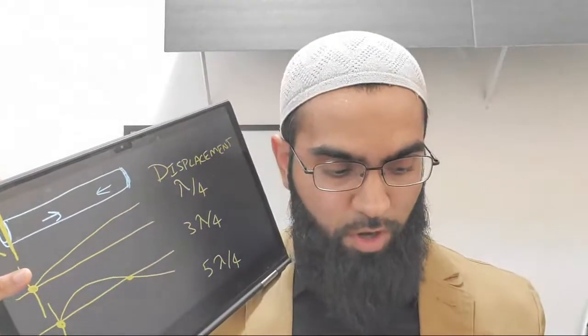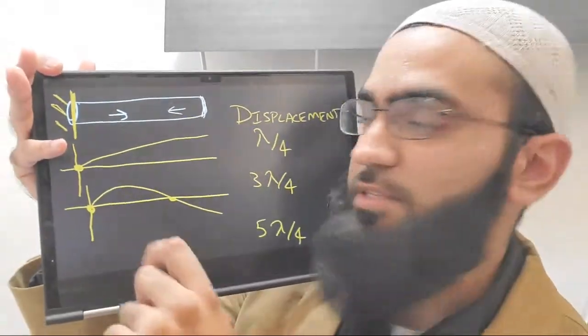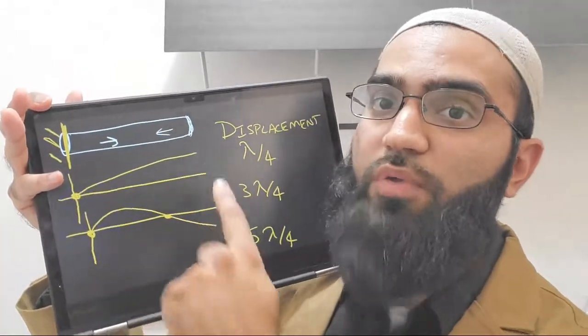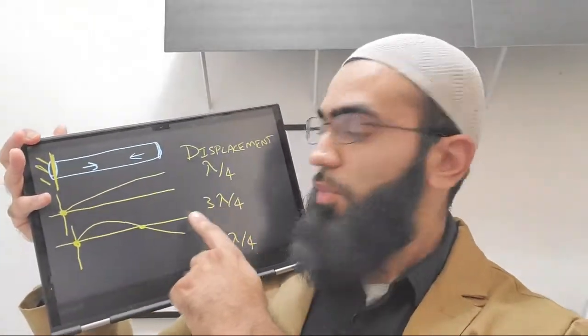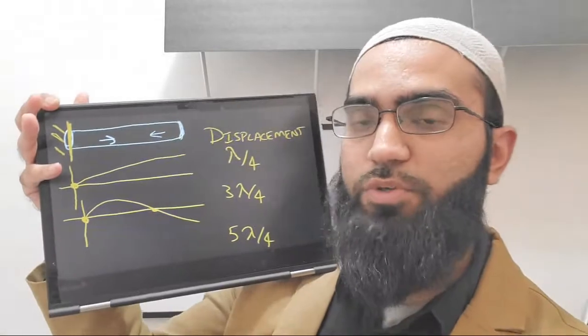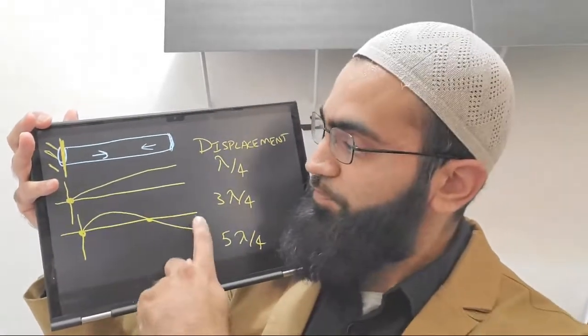The mode of oscillation, or the mode shape, which is excited in this case, is a quarter wavelength. So the quarter wavelength is also pretty important for the design of your transducer, especially for horn design. Utilizing and understanding these wavelengths, putting your nodes specifically at the piezos, and also your antinodes, which are the maximum displacement points, is going to be important. Obviously they're going to be at the edge, but also at those component interfaces in the transducer. And I'll describe that a little more. If we go to the next wavelength, it's going to be 3 wavelengths over 4, and that's going to be the next permissible mode in this case.